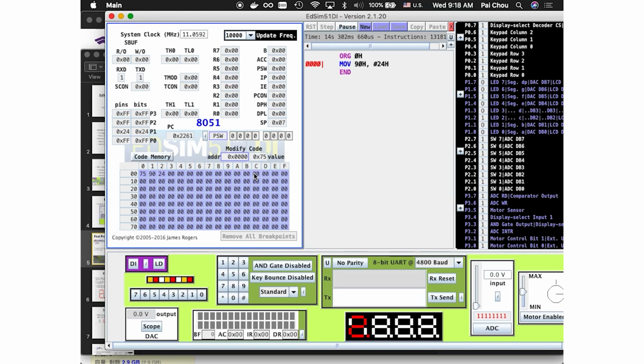Now in this case, 8051 happens to define 00 as a no-op, which means it doesn't do anything. But it does something as a side effect: the program counter says, oh, no-op, then move on to next, and next, next. So that's why it cycles through the entire memory, then comes back up. Why? Because it ran out of bits. Once you reach the last instruction, FFFF, what happens? You increment by 1, carry a 1, 0, 0, but there's no room for that 1. It doesn't fit, so it comes back to 0. Right? So that's why it's cycling through. Okay, so you never knew that a single instruction assembly program requires this much knowledge, right? But that's what you should know from this very simple program.